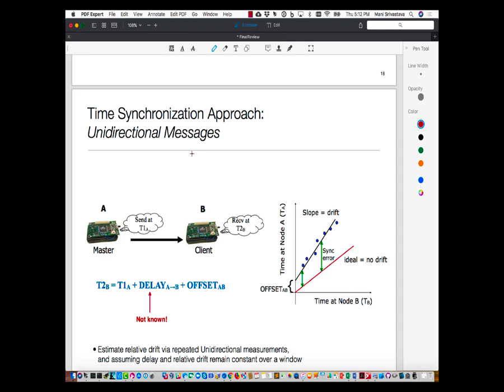And the reason I'm bringing this up is problem number one in the homework. You do have the situation where the Bluetooth radio is not up all the time. So you can approach it many different ways. One way is to send this information out once you actually have a connection, so that the delay is minimized. But you will still face some delay through the Python stack, because there is no way for you to tell the operating system to timestamp it when the packet is going out. You are going to timestamp and then hand it over. So then you can use averaging on top to correct for this.